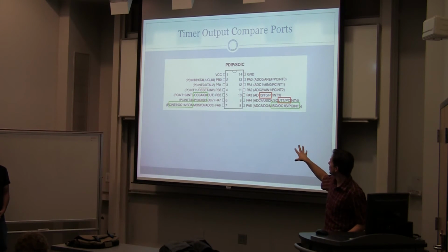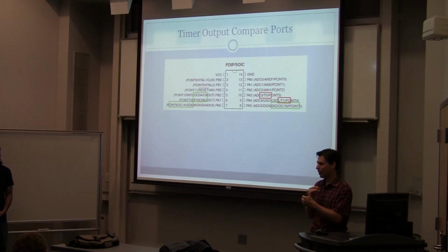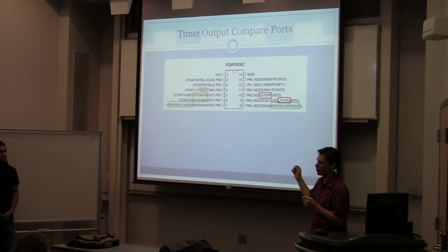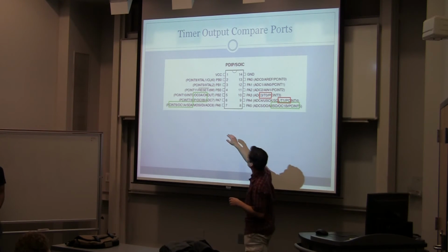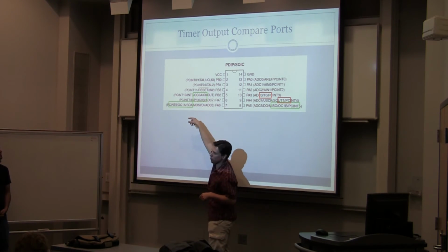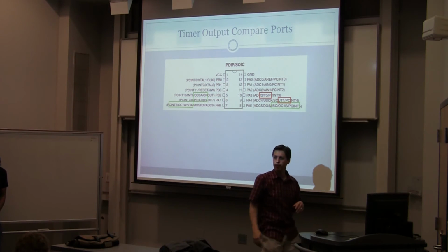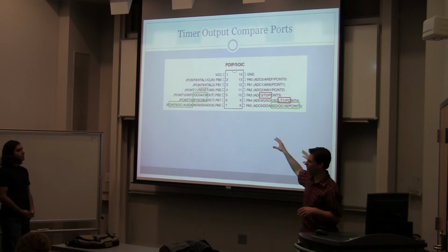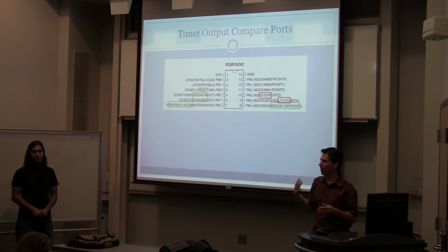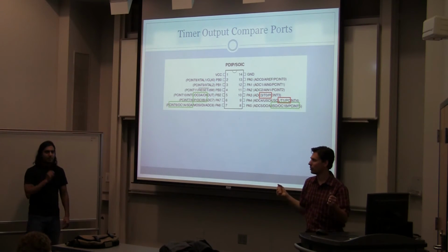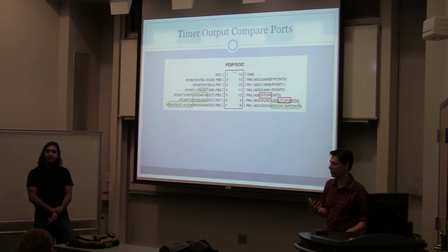This is actually important because if you think about, let's say you wanted to control a motor in your mini gadget or a buzzer, you would have to put the motor control pins, the pulse width modulation pins, or the buzzer pin on one of these. You couldn't just pick any random pin, because this is where the hardware allows you to make very high frequency pulse width modulated signals, which you need for a buzzer.